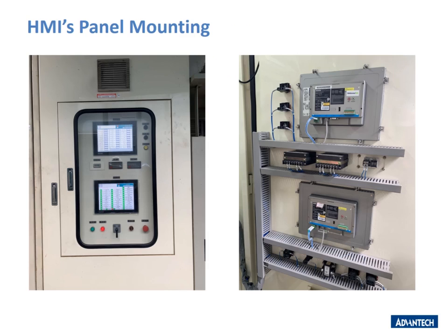In the first picture, it shows an application where the HMI is installed on a cabinet. The pre-assembled seals allow high IP protection against water and dust without big effort. In this way, the panel can be manipulated without a risk of damage. In the second picture is the installation seen from inside of the cabinet. The system as a whole can then be fixed with 8 screws from the inside or with clamping screws versus the front panel. This design type features extreme robustness and is particularly suitable for quick installation.